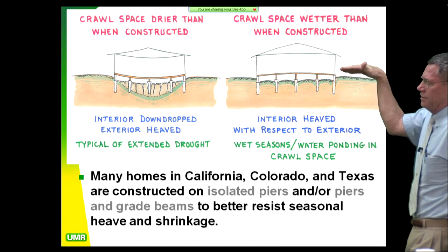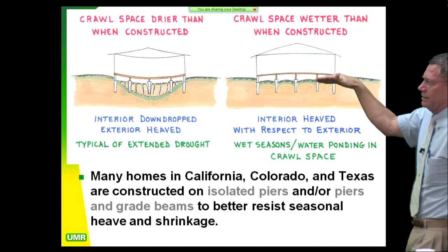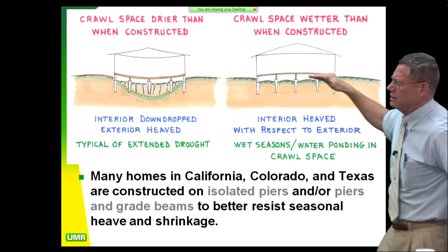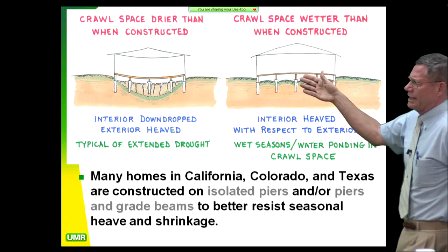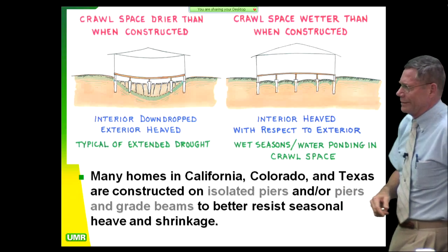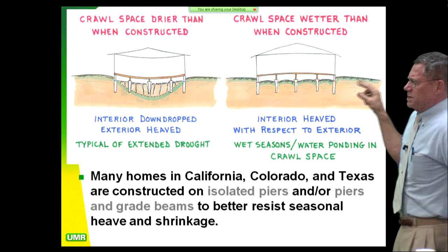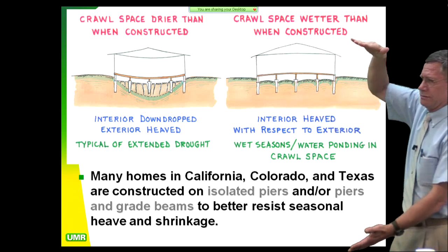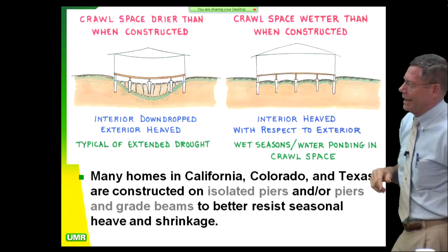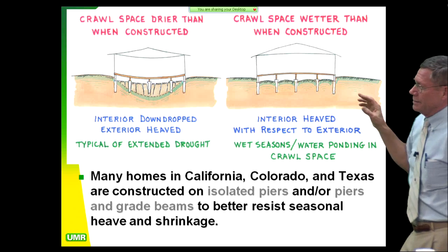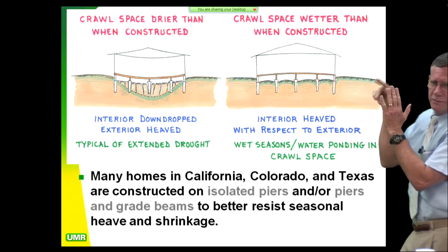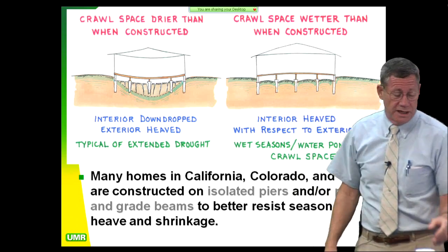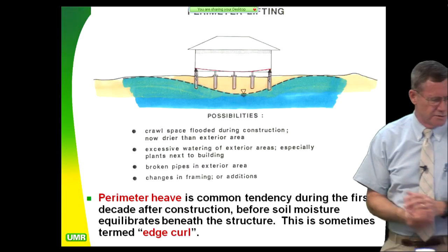They're watering outside. Notice how the yard level is slightly higher than the crawl space. That's always a bad situation for entrapping moisture under the house. And so in this kind of case, you get interior doming. So nowadays we put internal tie beams all the way across here, and you want to have like a nice 30-inch tall tie beam. That's what I used on my house out in California, so that I have a big section modulus, Mc over EI, to resist the bending, and tie all these things together.